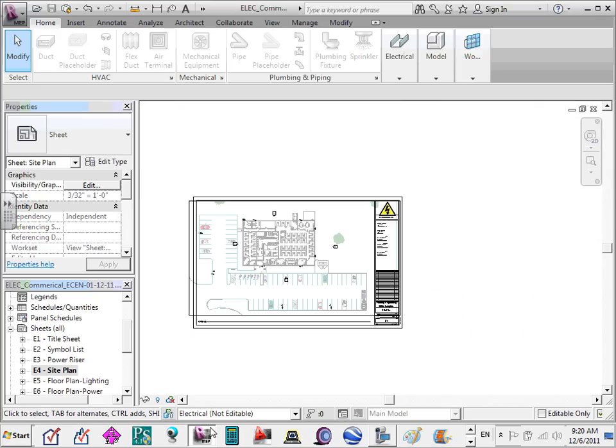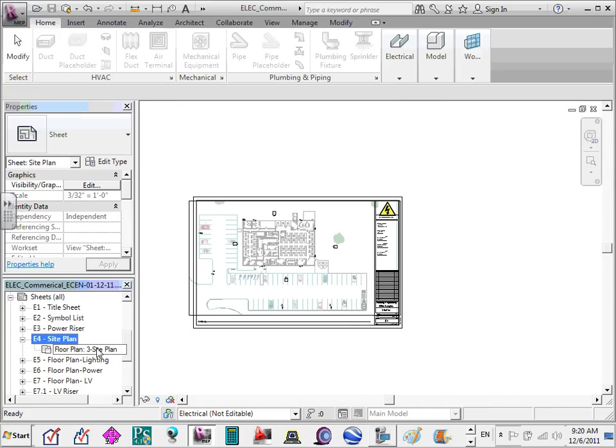That's your site. Now, if you expand this, what do you expect to find underneath it? You're going to find a floor plan. There's two different plans: a drafting view and a plan. A plan is part of the model. A drafting view is part of nothing. I can do a drafting view in anything. So here's what we did, Chris. We took the model and shaved it at, I think, 4 feet in this case. We expand the model to include the parking lot, and we start working on it. That's what they call the plan view 3D.